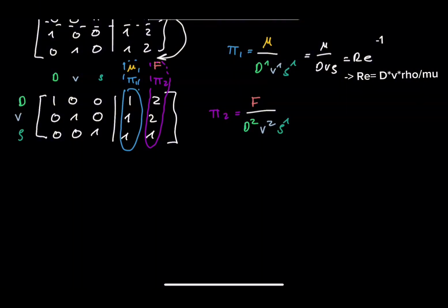Finally, we rewrite the result in a meaningful form. The drag coefficient is a function of the Reynolds number. This single statement explains laminar flow, turbulent flow, experimental scaling, and similarity laws all at once. That's why the Reynolds number appears everywhere in fluid dynamics.